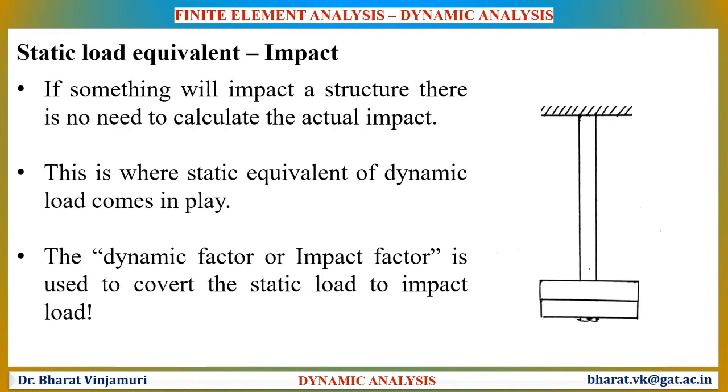Let us now understand what exactly is static equivalent load or impact loading. In essence, if something will impact our structure, you may not have to calculate the actual impact. This is where static equivalent or dynamic load comes into play. The idea is very simple. Just increase the load with a dynamic factor or impact factor. Then you can treat this as a static load in the analysis.